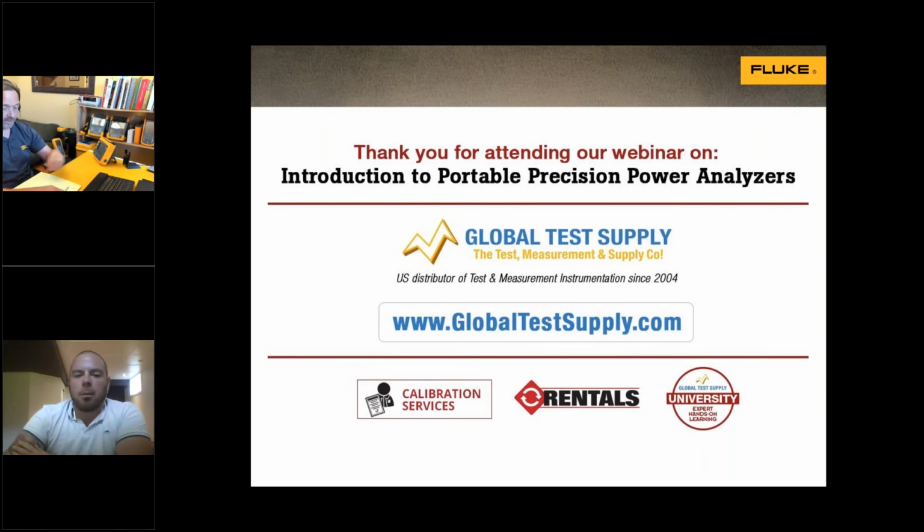Oh, sure. Well, it depends on what type of measurement you're making. The original point of the Norma design was to support variable frequency drive measurements, but usually those aren't going much above 8 kilohertz at the most. So 500 kilohertz gives you quite a bit more bandwidth. In the past, customers who have had very varying frequency measurement requirements, the oscilloscope has always been the go-to, like a Fluke 190 series.